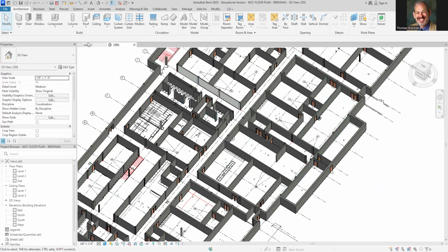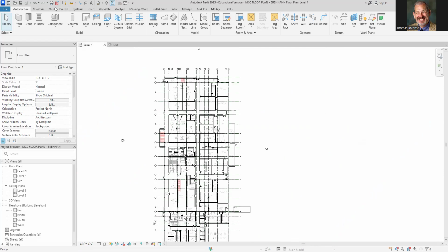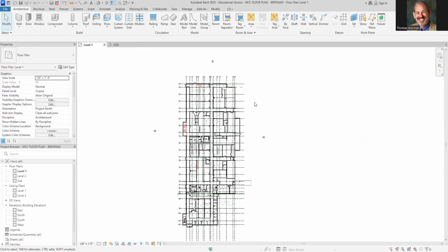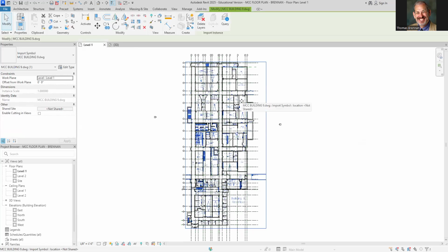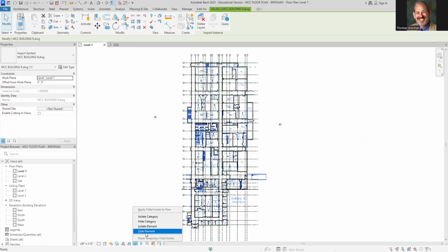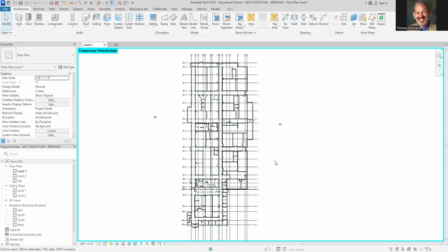All right, so over here, we need a floor. Just to show you how we do a floor, we did this before. To make it a little bit easier, I'm going to grab the CAD plan. To grab the CAD plan, you just hover over this until you see the CAD plan show up like that. When you click on that, the CAD plan lights up. Now we're going to hide it. To hide it, we go down here to the glasses. We're going to hide that element, and then you won't see that anymore.